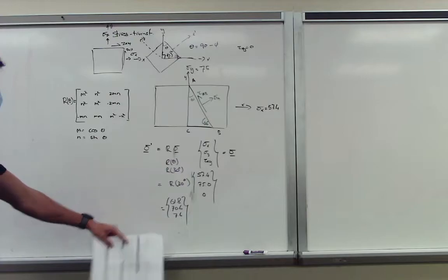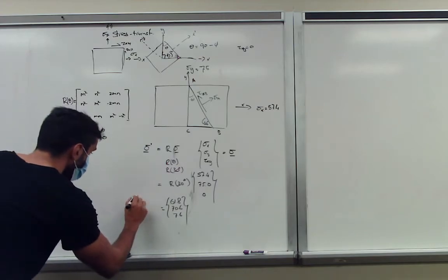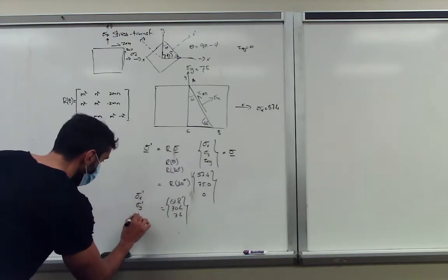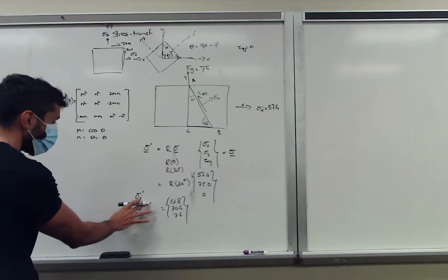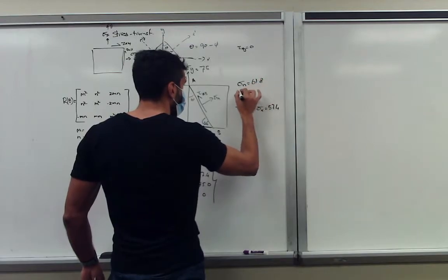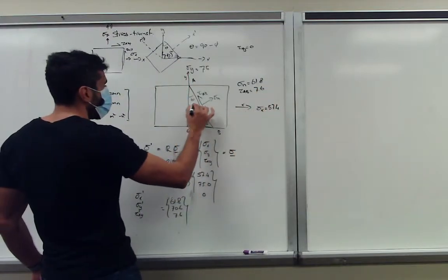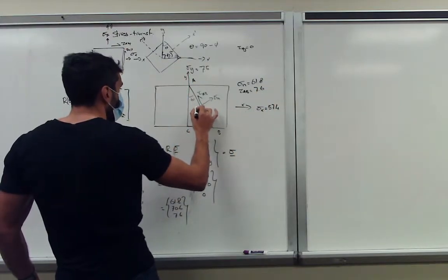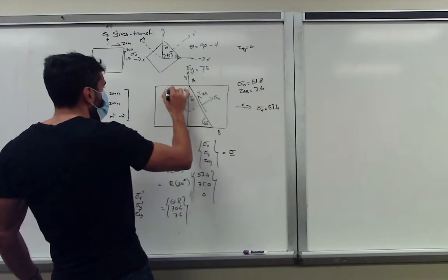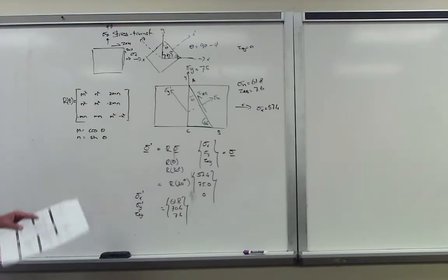transformed stresses. So in this case, what do these numbers represent? Well, first of all, this will be your sigma x in your transposed system, your sigma y in your transposed system, and your tau xy in your transposed system. So in this case, sigma n equals 61.8 and tau AB equals 7.6. And if you would draw another axis, looking at this sigma y transposed, that will be your second one, which is 70.6.